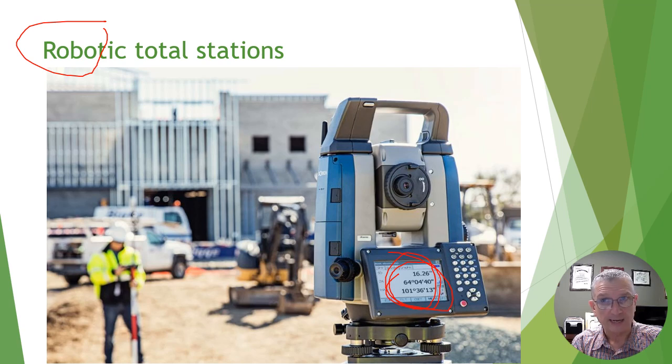This is how an angle reads out a distance. There's a little sine cosine encoder wheel that's mounted to the top of the plate of the instrument where it turns around, and that computes the angle and displays it. That's adequate to explain to most non-surveyors. That's easily enough to understand. A little brief explanation about how an EDM transmits a beam and then computes a distance. That has not changed since the 1970s, when EDMs first began to be widely used. And they weren't very widely used then, really, until the 80s.